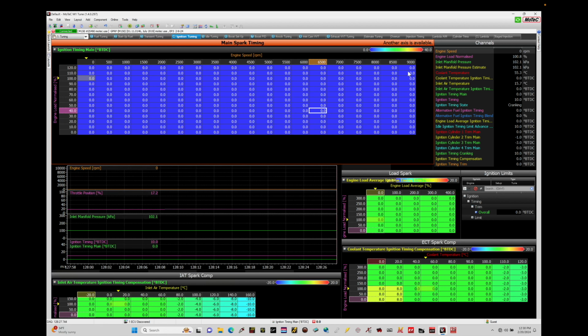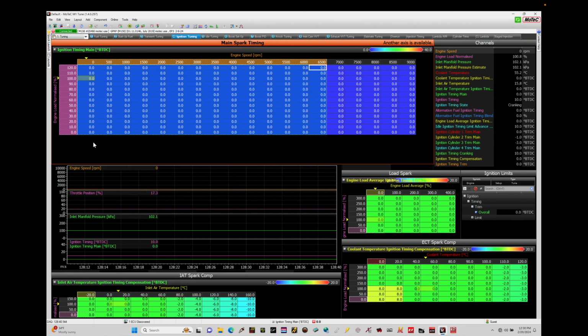I anticipate revving the engine to 8,500 once VTEC's active. Now VTEC's disabled right now on purpose just to map out and dial in the low cam or non-VTEC operation. Realistically, we're not going to go above 6,500 here during this tutorial with our low cam or non-VTEC. So we need to really sort out the values here. Obviously, we're going to extrapolate those values into the higher RPM where VTEC's going to actually engage and operate.